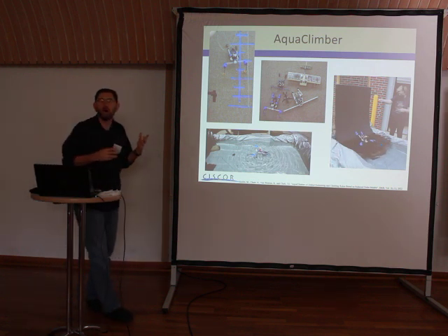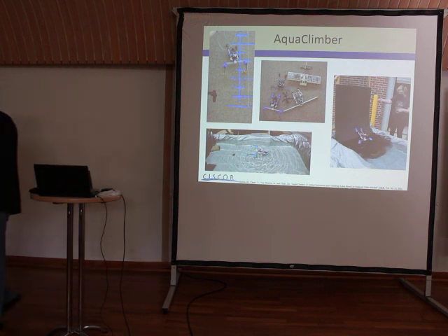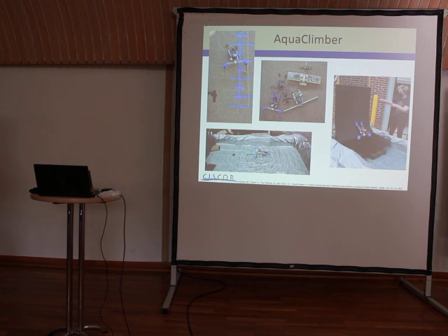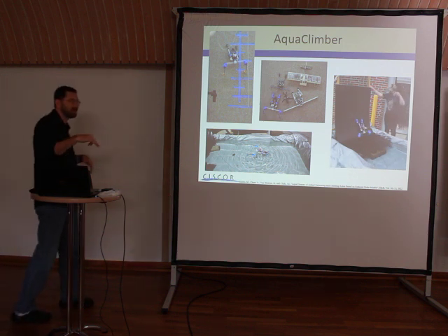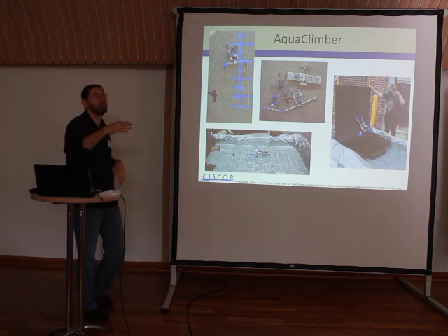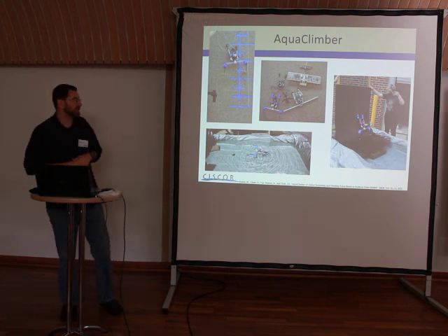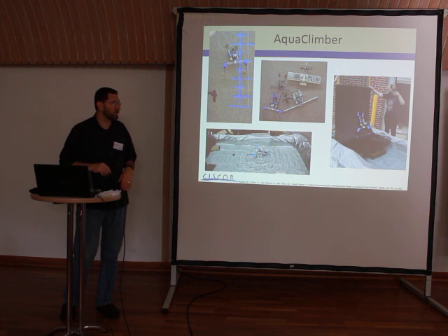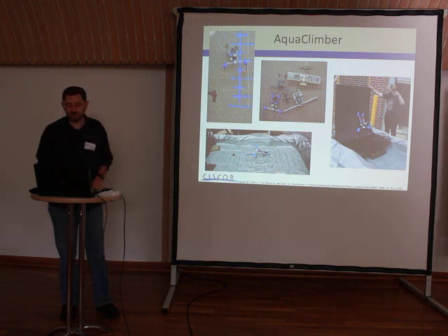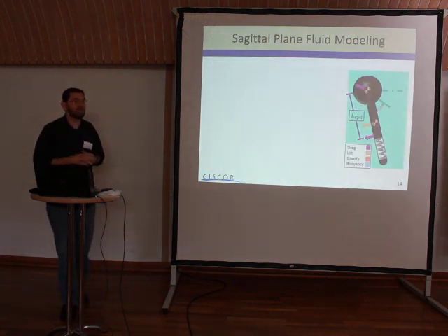Note that this robot only has two active degrees of freedom. One motor controls the front arms, moving them in phase lock with a simple sinusoidal trajectory, and the back one controls the rear legs, which controls the relative roll of the body. For swimming, this allows one foot to leave the water for more efficient retraction, and during climbing we lock those, so you can do the standard bipedal dynamic climbing. Okay, so that's the horizontal plane.